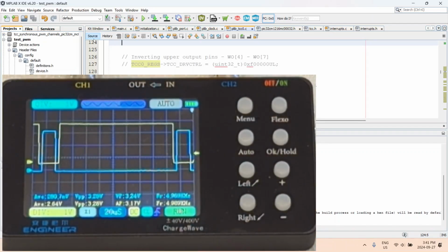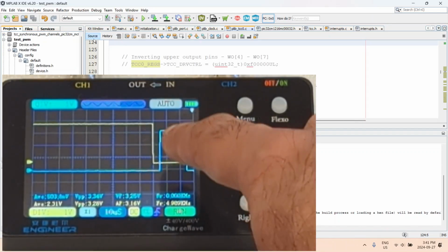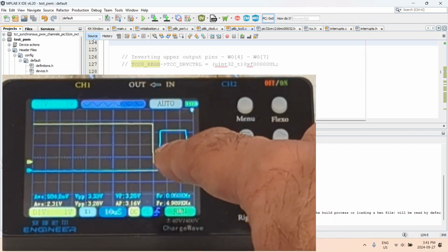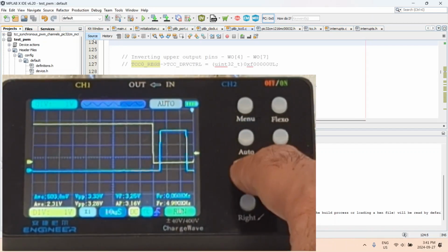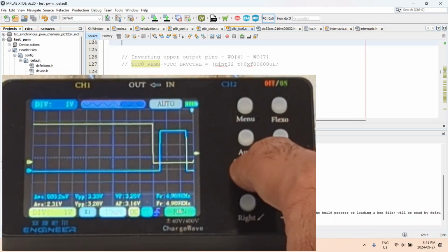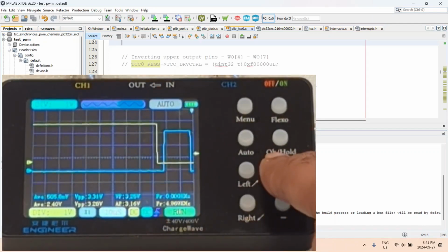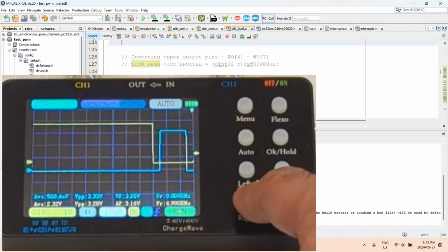And you will very clearly see there is now a dead time, right? If we zoom in a little, you clearly see that the rising edge of this blue waveform is delayed after the falling edge of the yellow waveform, and vice versa as well. So for example, if I go all the way up here and I scroll, unfortunately this is how much my oscilloscope can do.